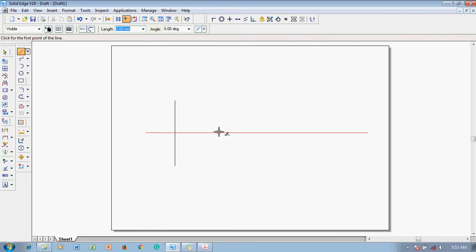And the second projector, now you can see this is a symbol called point on element. Starting from this line, one more projector is going to be drawn above the XY line, and the third projector was also above the XY line. Let me draw it above the XY line, and the fourth projector was below the XY line. Starting from the XY line, again point on element, just draw a line. Now you can see the dotted lines that we are going to get here.